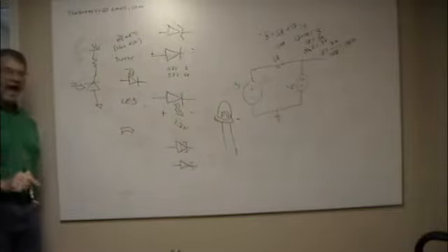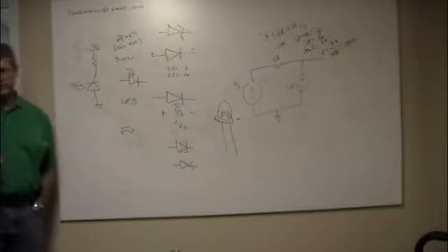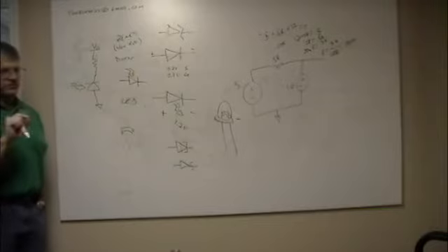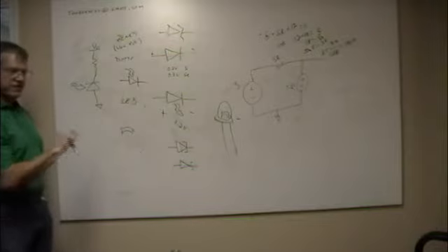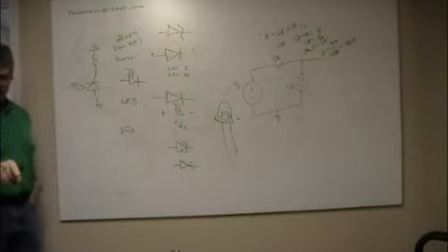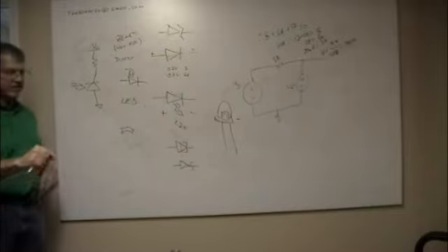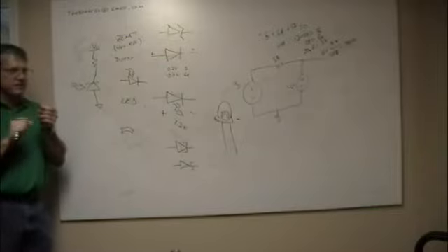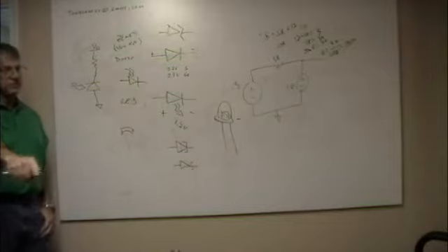The truth is, every diode will do that. So if you're using those little diodes, you'll see them. Usually they're germanium, usually they're fast switching. They have a glass case on them. So just like this light emitting diode, you can look at it and you can see the junction in there. In fact, it'll happen with these too. When light hits them, they conduct.